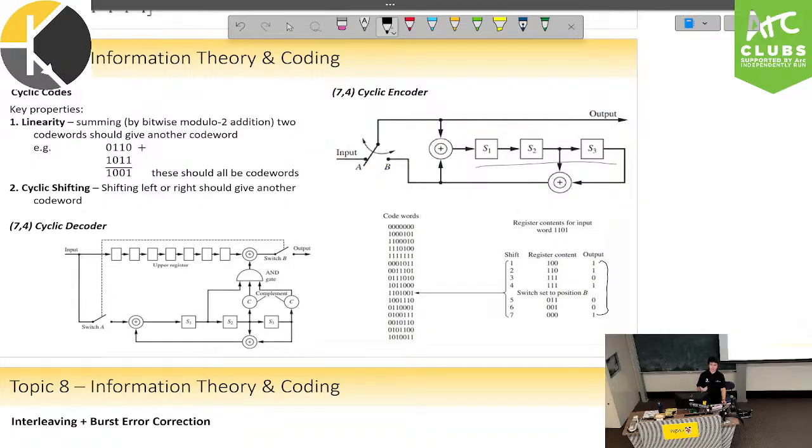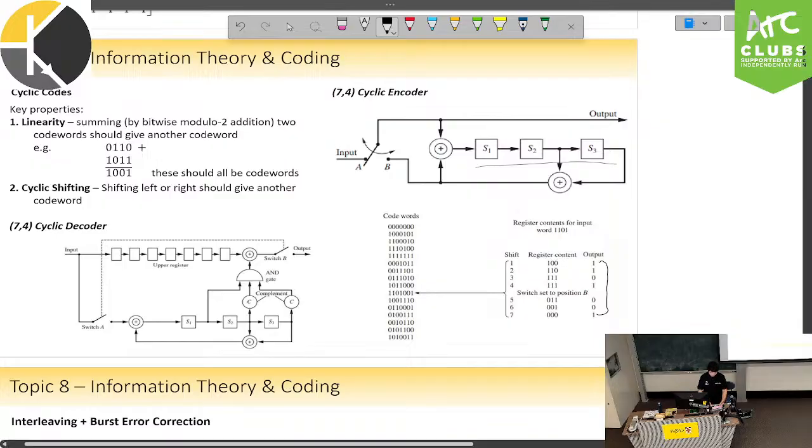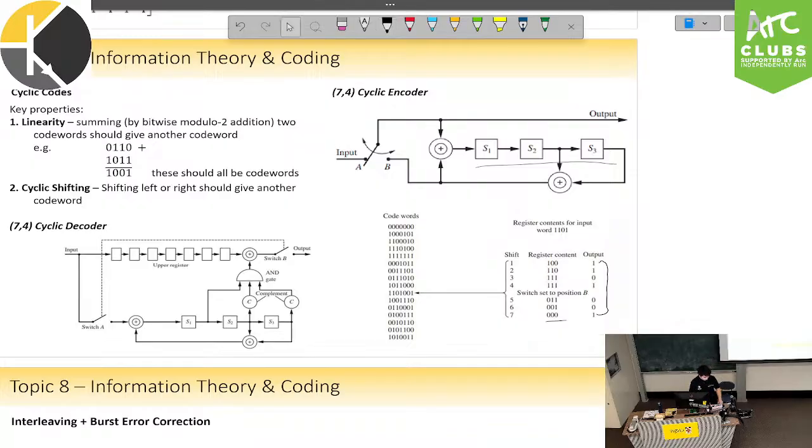So it's a way of generating unique code words for certain codes, given how it behaves. If you wanted to make this a 4-bit encoder, then you could add on another shift register and see how that goes. And then as soon as you hit it to B, you just run it until it hits all zeros, because it's going to flush to zeros. It's a very cool way of working this through.